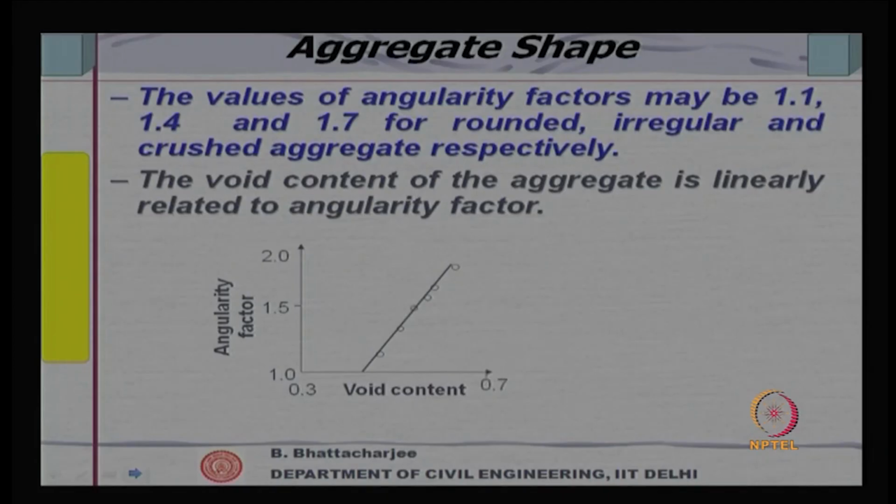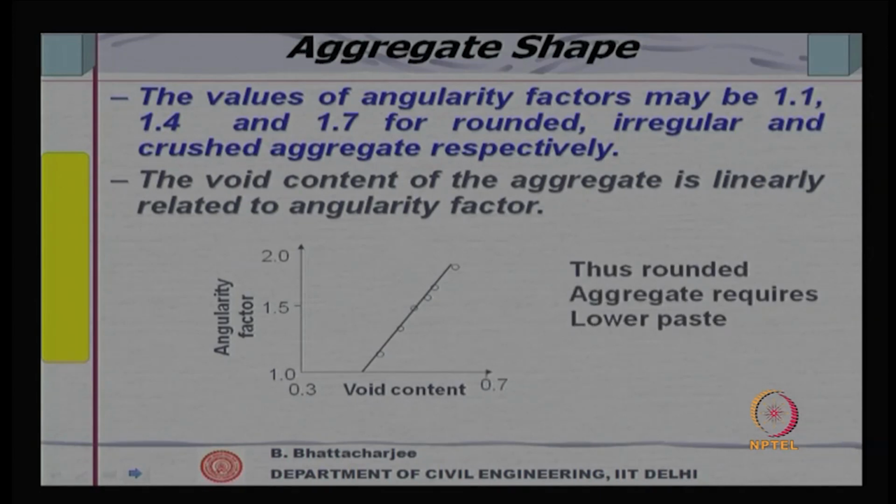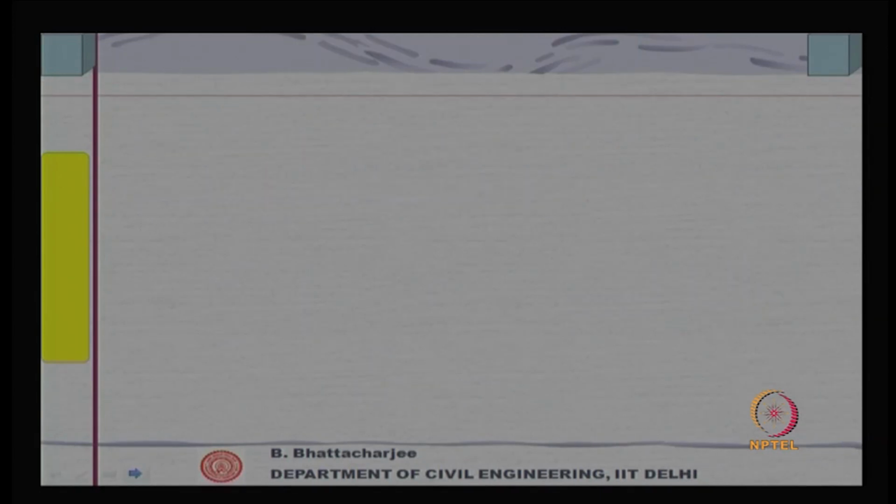Now, the more the voids, the more paste would be required to fill in the voids, and that is why shape is very, very important in the case of concrete, and that is why you are looking at shape. The size has got a role also, and we shall look into that role of the size.